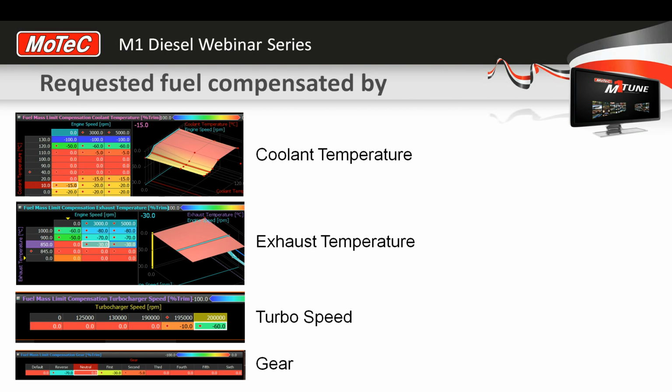So in an ideal world we'd run our turbo at the maximum speed possible all day long and then just add and subtract fuel to suit. So turbos are a gigantic consideration with diesel tuning. It's a very big topic, and you are constantly looking at boost control and turbo sizing to work in relation with injectors and fueling that you've got.